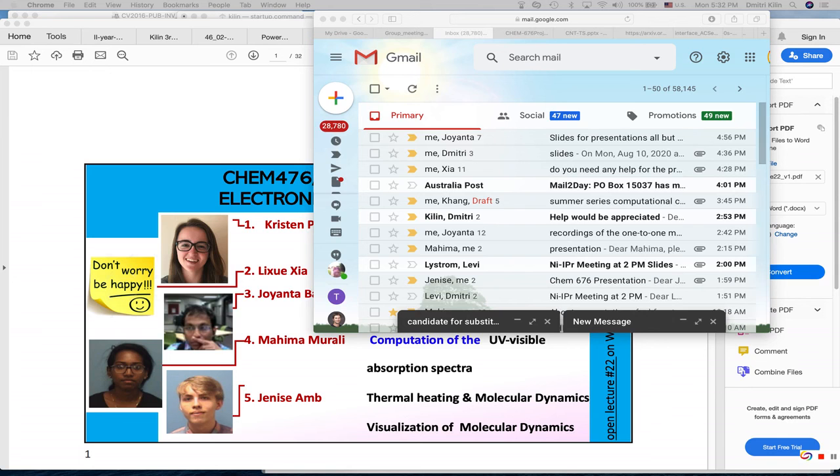Part 4 of the keywords is about special properties. In many calculations, we want to get special properties of the system. The first example is the calculation of partial density of states. We need to set ICHARG to 11, which means to read the CHGCAR obtained from a previous calculation. And then we need to set LORBIT to 11, which means to calculate the projection of the density of states.